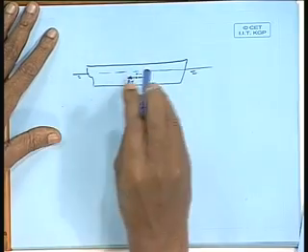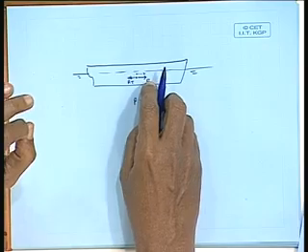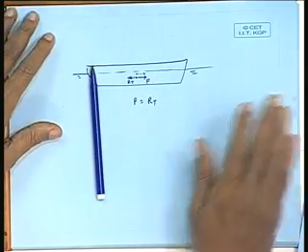Okay. But if I am maintaining kinematic similarity of flow, then whatever trim the ship will face, my model will face the same trim, geometrically similar trim. Am I making myself clear? So, when I am talking of this trim, this is in addition to that trim. All we have to take care is this does not cause any trim. So, as I said, to about 0.3 Froude number, there is no visible trim of the vessel and there is no visible trim in the model.